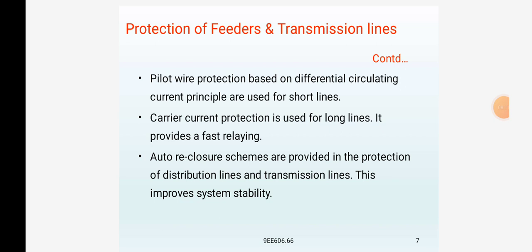There are two main schemes of bus bar protection, namely differential protection and frame leakage protection. The differential protection is based on the simple circulating current principle that during normal load condition or external fault condition, the sum of currents entering a bus equals the sum of those leaving.